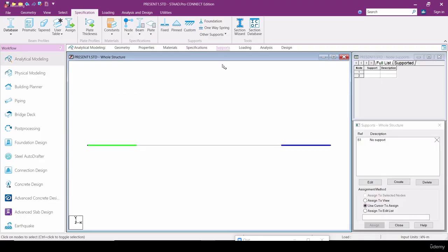And the next thing, the supports. Yesterday I told you about a simply supported beam. Can anyone guess what the supports to a simply supported beam are? Most people will say both are pinned connections. That is wrong, if you talk technically. A simply supported beam will have a pinned connection at one end and a roller at the other end. So what is the difference between a pinned connection and a roller?